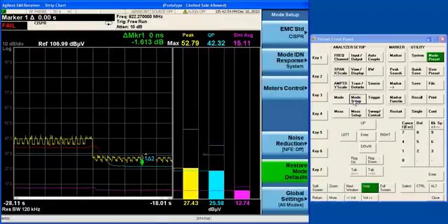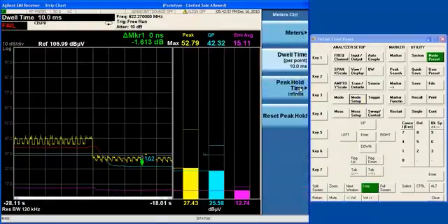Now, the resolution of the meters is controlled by the meter dwell time, and the smallest dwell time is 10 milliseconds. So that means you can have a resolution of 10 milliseconds, which is plenty of resolution for doing click measurements. So you can use the strip chart to do click measurements. And you can also use the strip chart to do a capture of data from an antenna while, for example, a turntable is rotating. And it frees your computer from the need to keep up with that turntable.